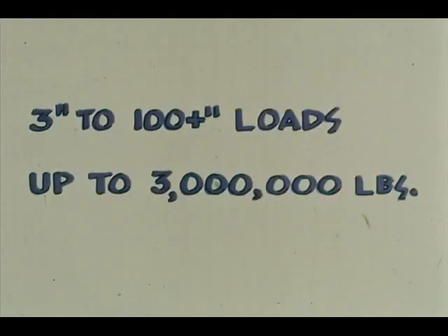The Kingsbury type bearing is generally manufactured in sizes from about 3 inches in diameter, sustaining loads of a few hundred pounds of thrust, up to bearings in excess of 100 inches in diameter for the hydroelectric generators, supporting loads up to 3 million pounds and more.